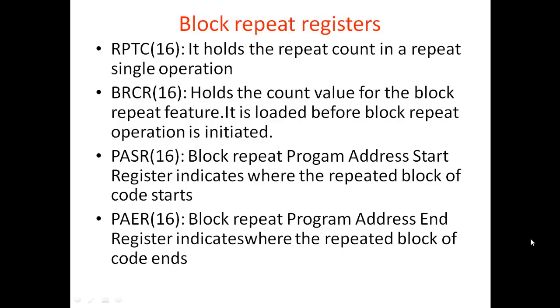Block repeat registers. It has 4 important registers: RPTC, BRCR, PASR and PAER. All are 16-bit length. RPTC holds the repeat count in repeat single operation and it is loaded by the RPT and RPTC instructions.